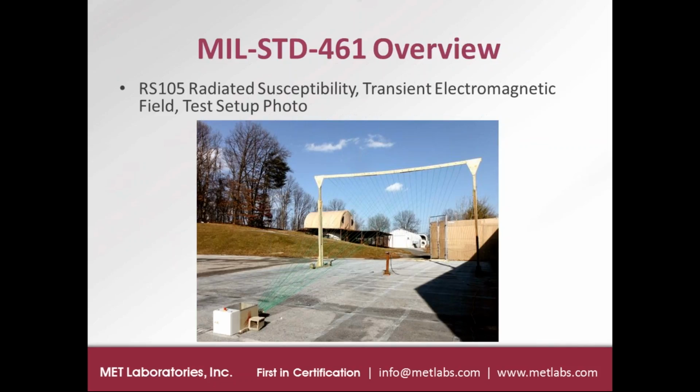When you conduct the test outdoors, you have to construct a ground plane. So for this test, there was a ground plane of about 100 feet by 50 feet, constructed out of wire mesh rolls. And then when you do this test outside, you also have to respect a clearance around the test setup for any other electronic equipment, and then a further clearance for personnel.